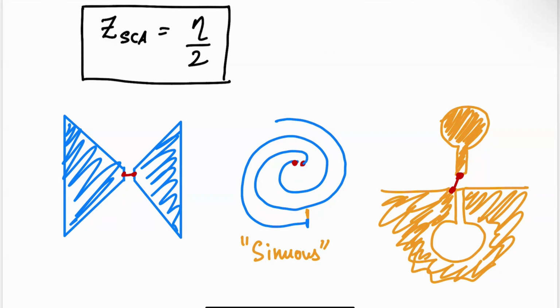Okay, now one of the big drawbacks of Babinet's theorem in these kind of antennas is that they are planar, right? Which means that they radiate in two directions, both up and down. So if these are in the XY plane, then they radiate both in positive Z and negative Z. And that's not always desirable. In many cases, you don't want to radiate on the quote unquote back side, you don't want any back radiation. So you want to put a ground plane. But once you put a ground plane, then it becomes a 3D structure. Once you have a 3D structure, the Babinet's theorem we developed here doesn't really apply anymore, right?